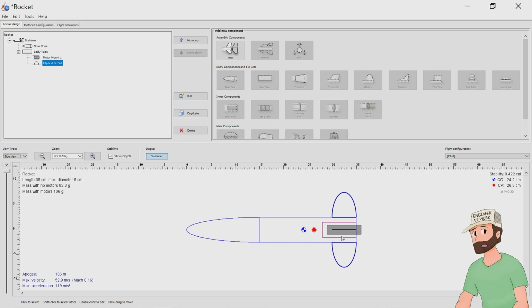There are a couple different things that affect how high we go up. The biggest one is going to be how much drag we incur. There are two things we can fiddle with to affect how high we go: drag and our weight. The one that will have the most effect is the drag, because drag is proportional to how fast you are going squared. Whereas the weight is only proportional to how heavy your vehicle is, which reduces as the motor burns up. So those are the two things we can do to affect how high we want to go.